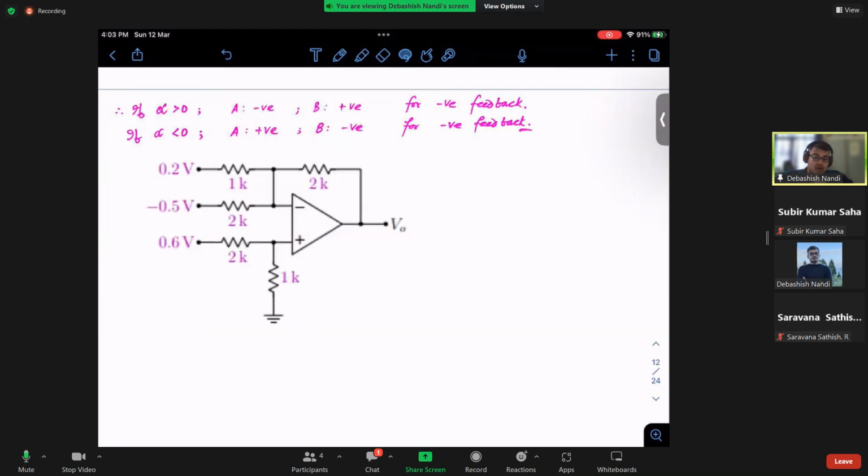So I need to find out whether this circuit is in positive feedback or in negative feedback, right? Let me copy some box. So let me remove the op-amp and the step 1, and I want to know what about these signs, right? So what I will do, I will apply a V-test here, and I want to see what is the feedback at this point, right?